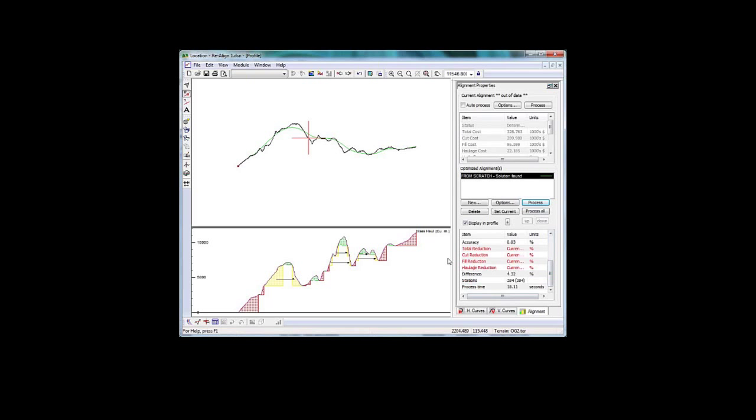No point comparing this with the original ground solution because that really is not a solution at all. But it has calculated a cost, $500,000 to build this, and that's based on those costs we put in there. It's important to note that the cost calculation is only for the earthwork. We're not costing pavement or culverts or other similar items. And from the point of view of finding the best alignment, those costs don't change much when you change the alignment. So they don't really change the best alignment. They just add to your cost at the end.